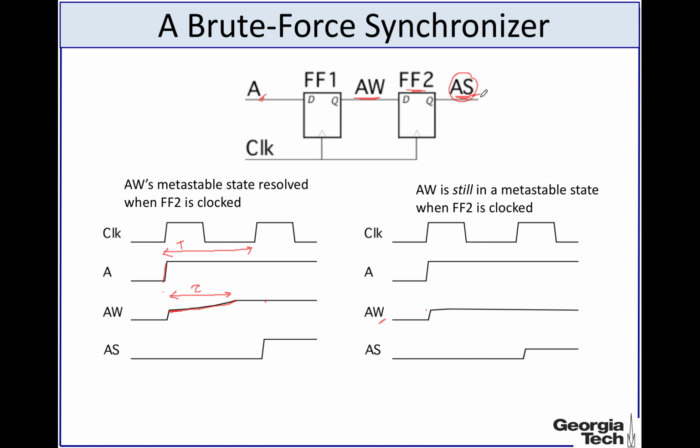And what we will see is that compared to 1 flip-flop, if there are 2 flip-flops, then the probability of propagation of this metastable state goes down significantly, and if we add 1 more flip-flop over here, then the probability will go even further. That's how we design synchronizers such that the metastability conditions do not, for all practical purposes, propagate to the rest of the circuit.